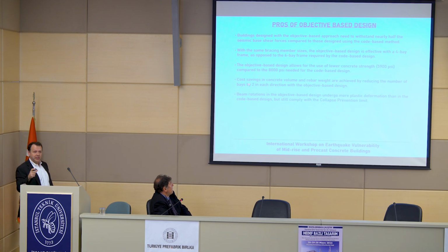With the same element sizes, same column sizes, same beam sizes for the moment resisting frame and for the gravity columns, the objective-based design was effective with a 4-bay frame, so 2 plus 2 in each direction, as opposed to the 6-bay frame required by the code-based design.